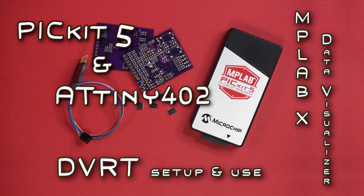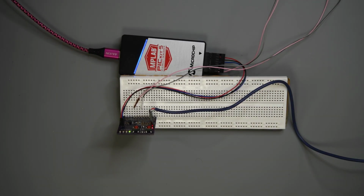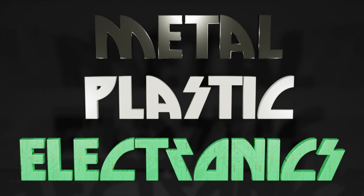I was very pleased with the MPLAB X data visualizer's variable streaming operation, but the data visualizer has a more advanced section, the DVRT session. The data visualizer runtime session will allow for the reading and writing of global variables, and it sounds very useful.